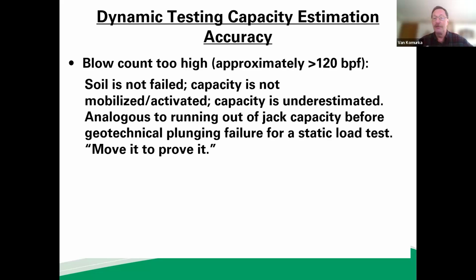So again, we had those previous two slides so that we can say that's analogous to a jack running out of capacity during a static load test. And the memory trigger, or cue, that I like to use is when you're driving a pile, you have to move it to prove it. If you're not moving the pile, you're not mobilizing its capacity, you're not proving its capacity. So you have to move it to prove it.